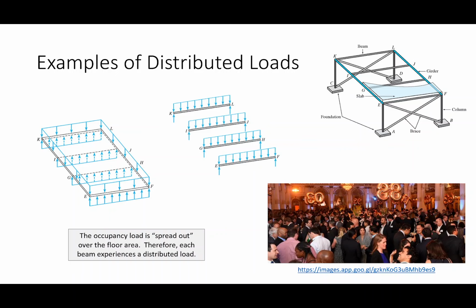And so as structural engineers, we have access to various codes and specifications that will allow us to ensure that when we're designing structures, we're all using the same type of load set. One of the most common examples of this is ASCE 7. You might hear this in a concrete design class or a steel design class. For example, if I'm designing a classroom, I might have a different load set than if I'm designing, I don't know, a library. I think I might have mentioned this earlier, that if we're designing a classroom, we might design it for about 40 pounds per square foot. So that's about the maximum foreseeable load that we would see on the floor in a room like this.